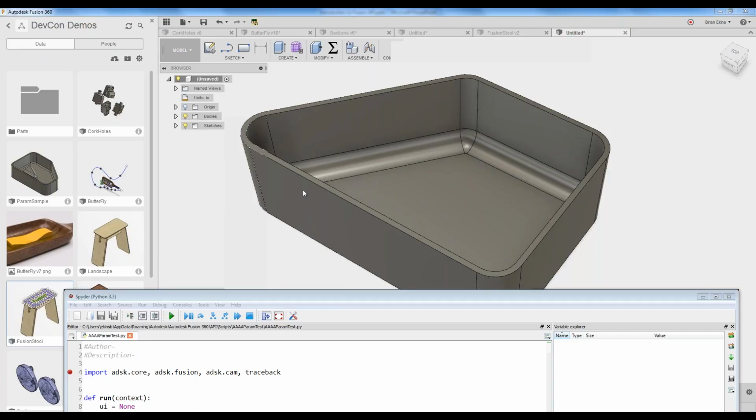So today, as I said, the API runs inside the desktop. And so the desktop has to be running to use the API. There is some functionality, and it's in the help. In that overview, there's a section called, I think, inserting parts from a web page or something like that. But it's a way, kind of from outside Fusion, to start up Fusion. But the Fusion client has to be running to access the API.